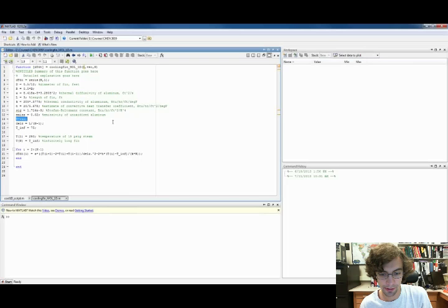So that might be an interesting effect to look at, because at the points where you have 200-degree surface temperatures for the fin, there's certainly going to be radiation from that. Although it might be minimal, depending on if this emissivity value is a fairly accurate one. You see it's pretty low, so maybe that radiation isn't a big deal, but it could be something that you look into.